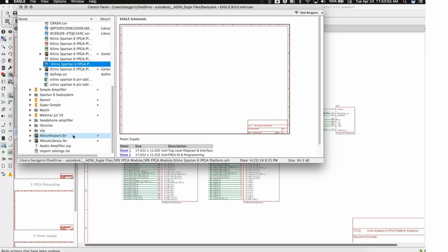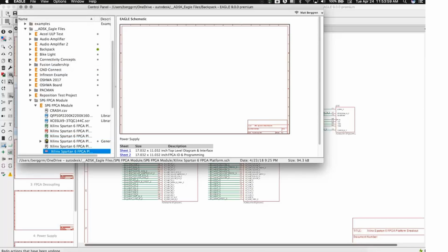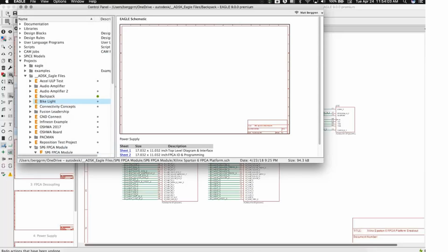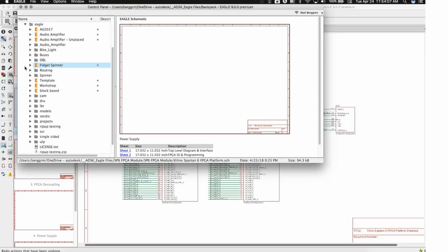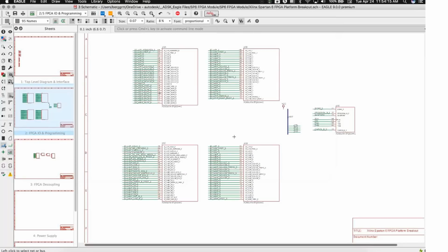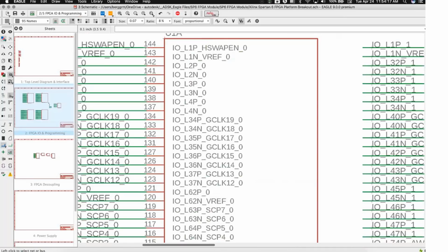But even now, Daniel, you don't have to do the whole next option thing. You can just left click wherever multiple items intersect, and then you'll see the cursor change, and you can right click through the various items. It'll go from smallest to biggest, and then left click to confirm the object you want. There's also an Alt option where you can hold Alt and start left clicking, and you'll see that it'll cycle through all the nearby items. So there's many ways to handle selection with nearby items right now.